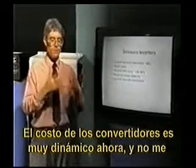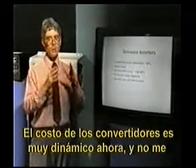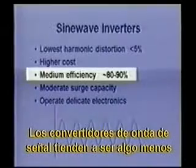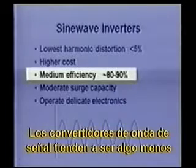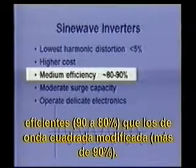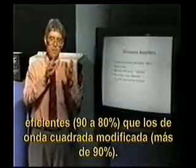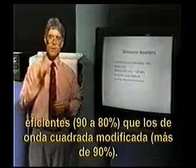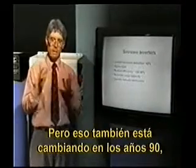The cost of inverters is very dynamic right now, and I would watch for the cost of sine wave inverters to come down. The efficiency of the inverters, in general, tends to be a little less than modified square wave inverters, in the 80 to 90% range, as opposed to, in general, above 90% for modified square inverters. But that also is changing in the 90s.